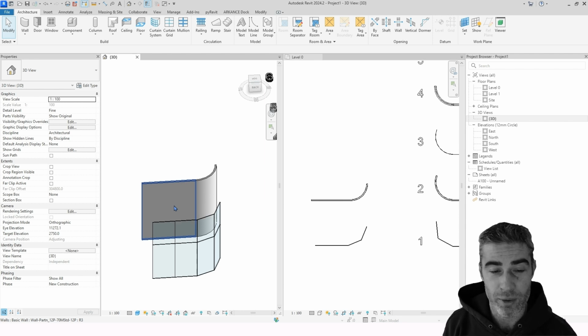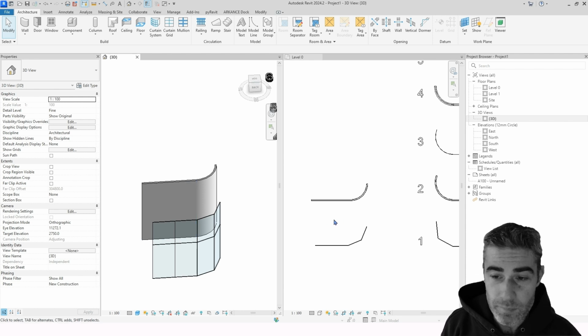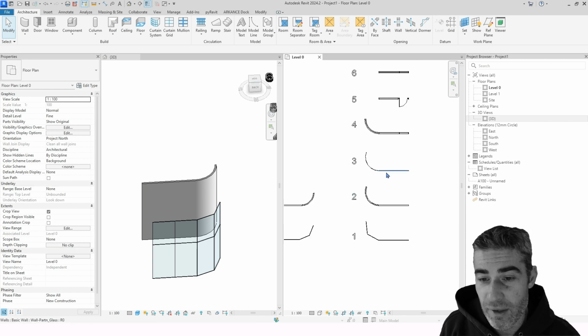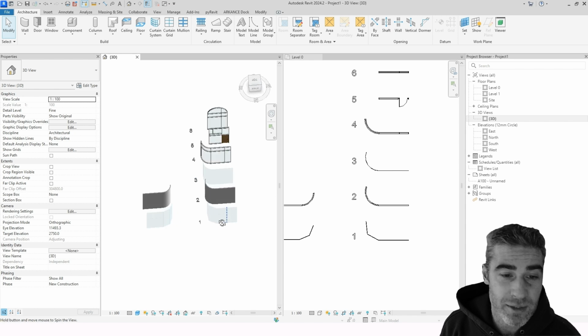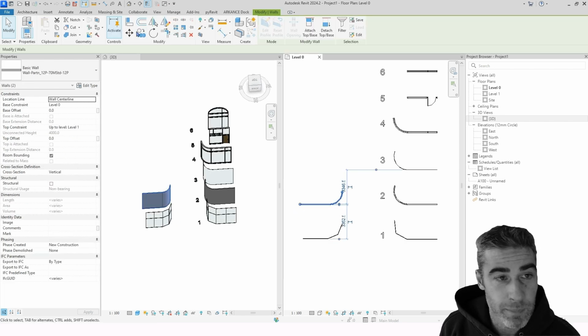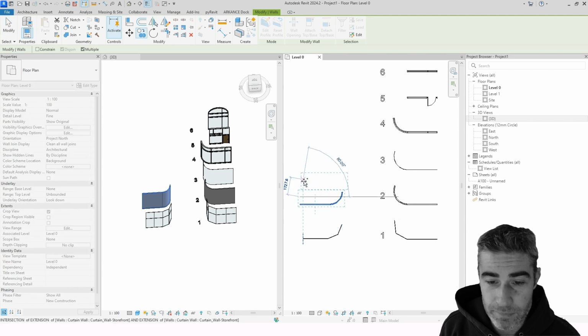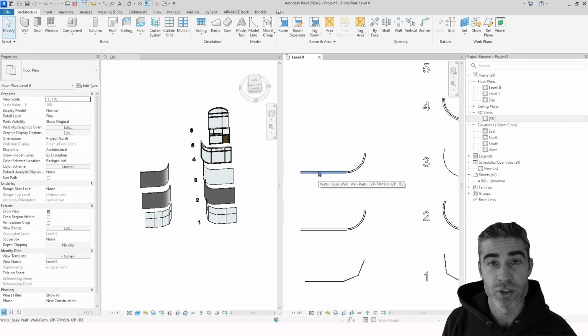So now where my thought process goes is, well, why don't we just change this wall to just glazing? So in step 3, you'll see that I've actually just created a glass wall. So what we can do is select the exact same wall. I'm just going to copy this up a little, to say around here. And what we want to do is modify this wall to just be a glass wall.